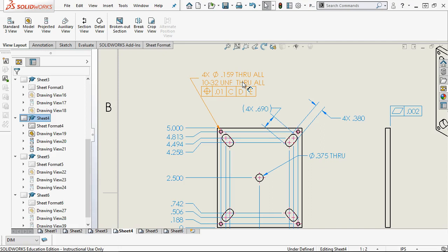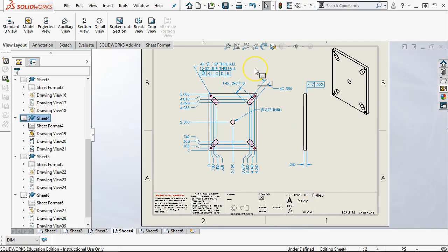And then, kind of thinking down the path is, how critical is it with a 10 thousandths positional tolerance, and I'm holding a reasonable class H6 tap. I should be within the tolerance zone and the pitch diameter of everything as we need it anyway. So we're going to stay with that one.